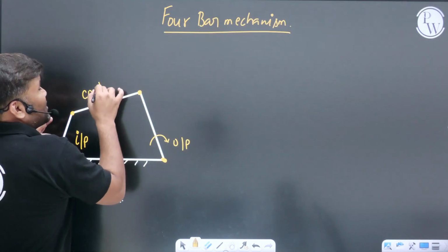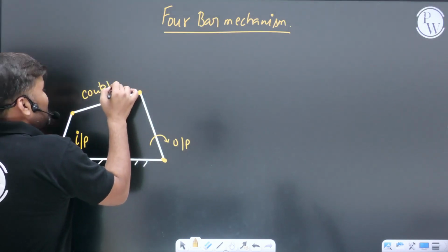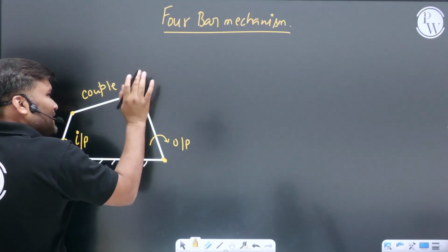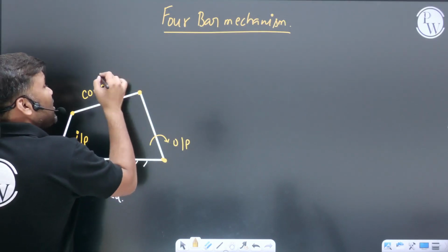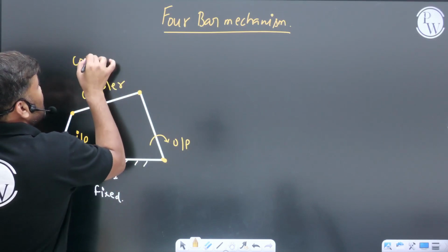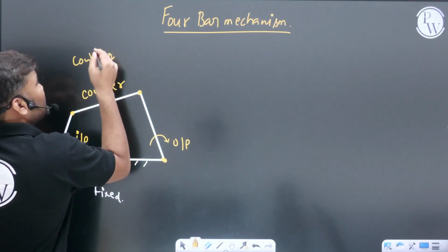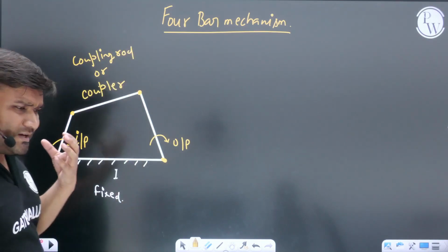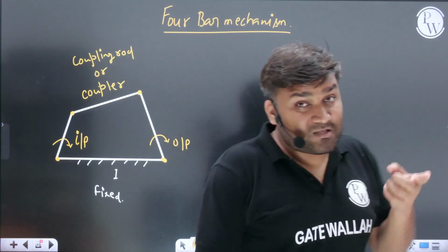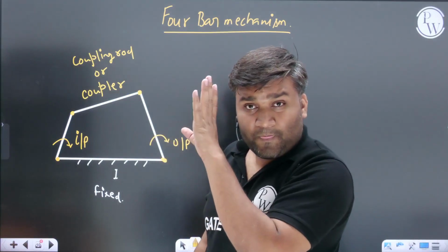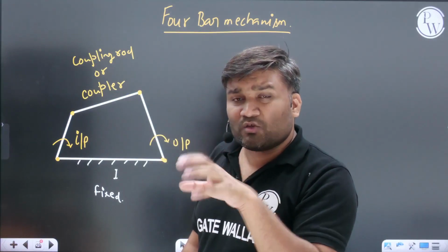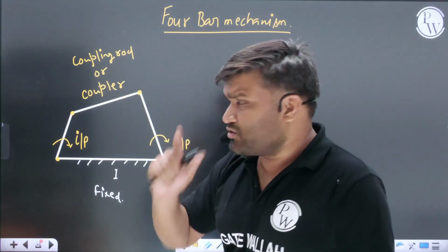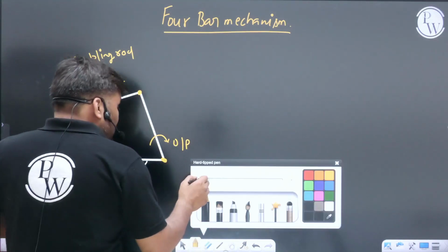Don't call it connecting rod. Many people, many innocent children, are calling it connecting rod. No, brother, that is not connecting rod. Say coupler, or you can call it coupling rod. Connecting rod, this word we will use when it is part of your single slider crank mechanism, the IC engine part. In IC engine we can use this term connecting rod, but till that time, coupling rod or coupler, only this thing you have to use. Okay,